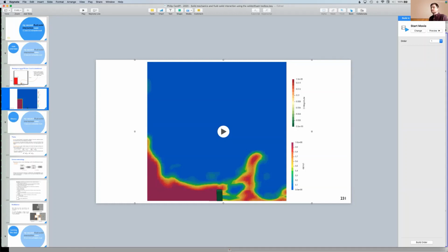A few more questions. In your flexible dam break example, is the impact of buoyancy on the vibrating solid accounted for? So I can see Hossein, you're asking this follow-up question. In the interFoam or interFluid class, the only extra thing we have to define is what the traction, or the force, is on a given patch. So for that specific fluid model, its definition of force, we need that to be able to use FSI.